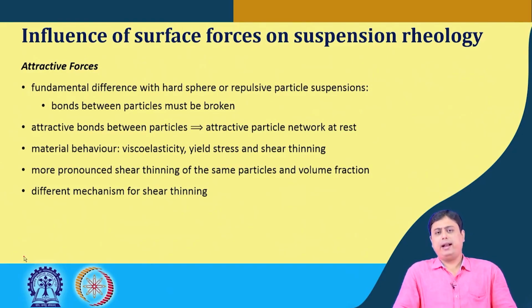Now, in the case of attractive force, the fundamental difference from the hard sphere or repulsive particles in dilute suspension is that here we have to break a bond between the particles. Because of this attraction, there is a bond between the particles, and if we try to alter its viscosity, we have to break that bond.